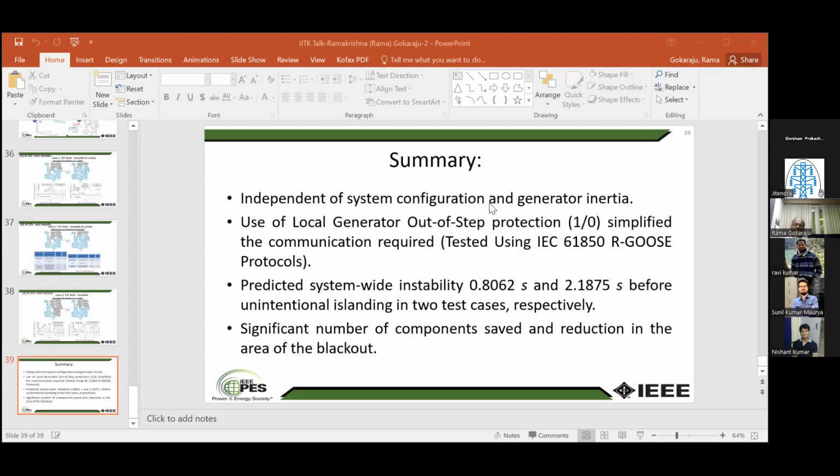And here, this is a transmission system. In terms of the loading we are implementing, the protection we have is the distance protection on the line, not overcurrent. If it is a distribution system, then we can have the overcurrent type of protection.